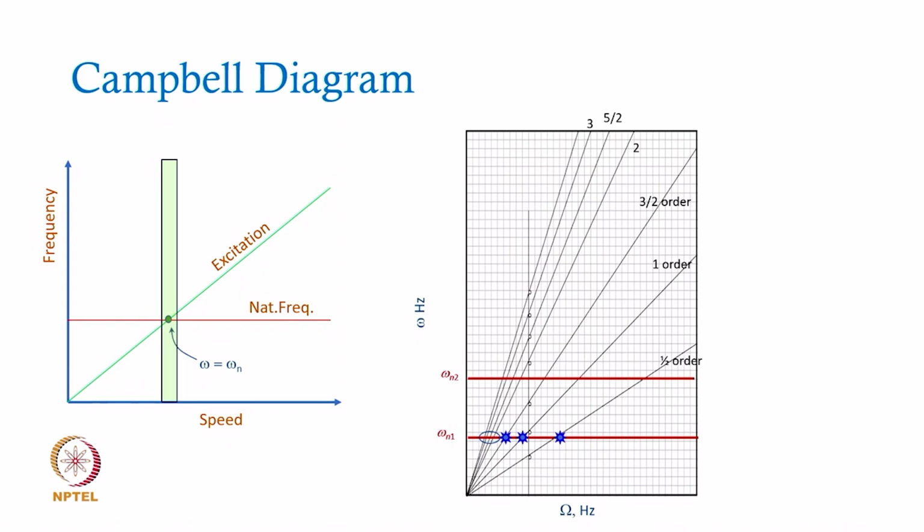Now, you may have another natural frequency, right. This is the fundamental natural frequency, first of the many. You may have another one, you may have another one, right, and then what do you get? A minefield of resonances, where to put your foot on, it is all scattered. I mean, you think of any position or any operating speed, chances are that you will bump into one or two or more of such resonances if you really look at the entire picture carefully.